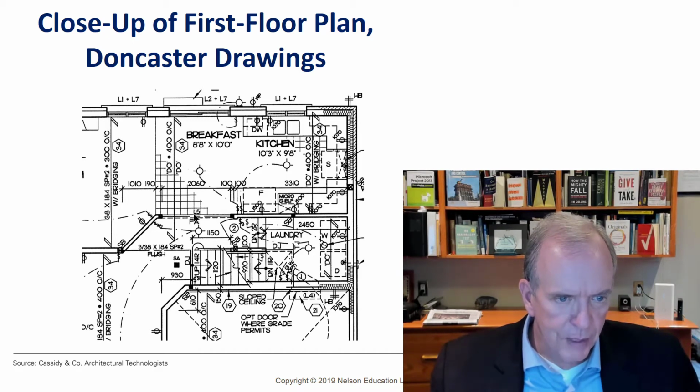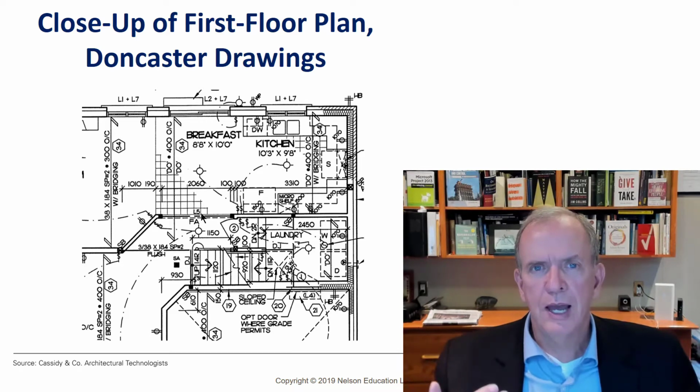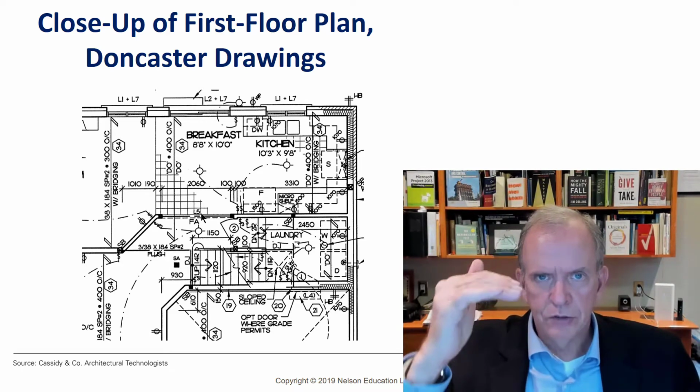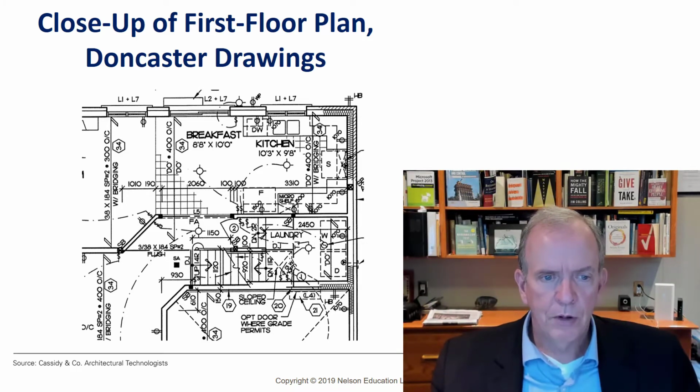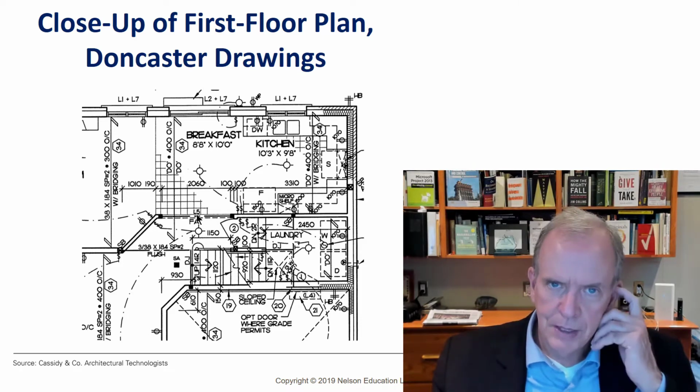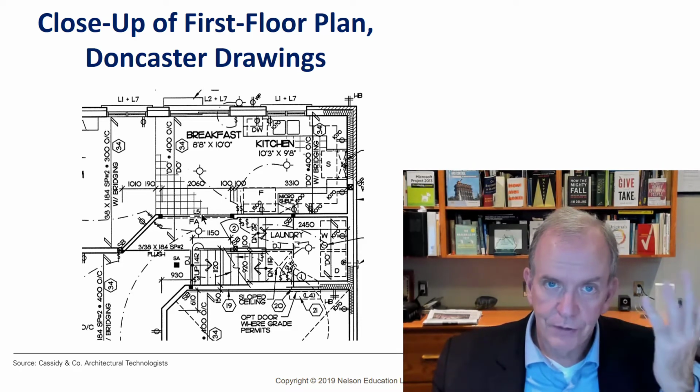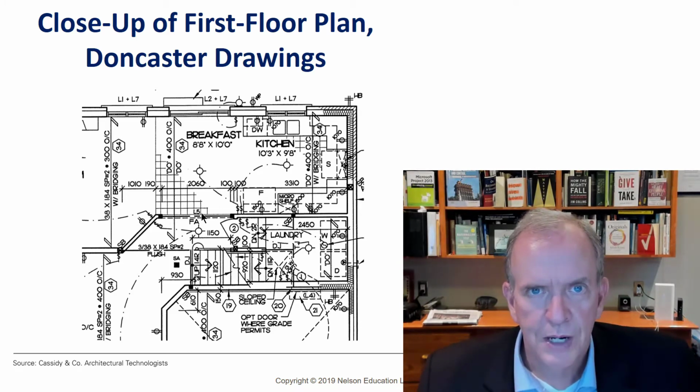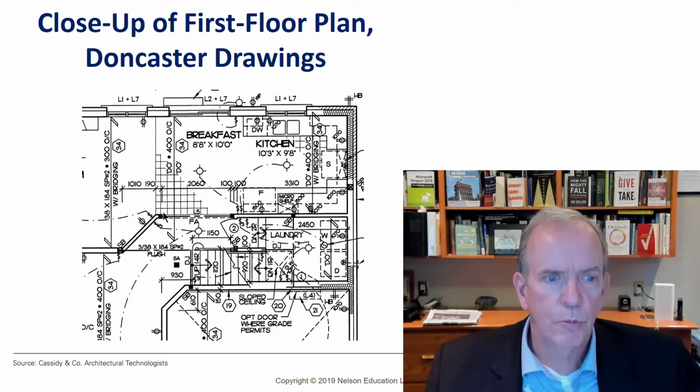So here's that lintel that I was telling you about. And if you look closely, it says L5. So you remember that chart we looked at in the previous lecture, and it said lintels, and it said L1, L2, L3, L4. Well, if you look at L5, it'll tell you the actual size of the lintel. And so that's either going to be, I forget what this one is, L5. I'd have to look at the chart myself, but it's probably 2x10s or 2x12s, judging by the opening.